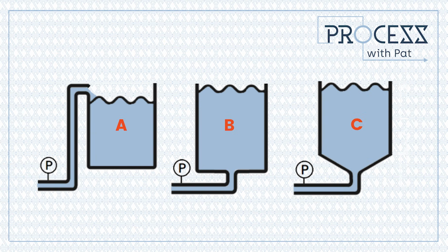If we're pumping this fluid, it's not necessary for our pump to overcome anything extra in one situation over the other. Even if we took a tank with a conical base, it's not as if we're magically somehow funneling all the pressure onto our inlet pipe. The force on our inlet pipe is still the result of that same column of fluid. The rest of the fluid in the tank is exerting its pressure on the conical section of our tank. So apart from some minor changes in frictional losses because the piping arrangements are different in these scenarios, the real difference in pressure in getting that fluid into our tank is almost negligible.